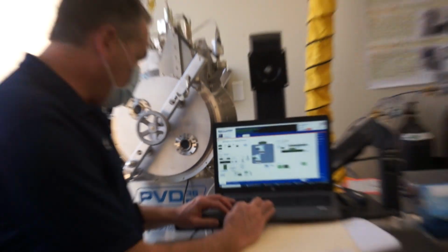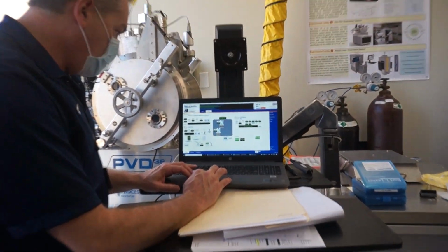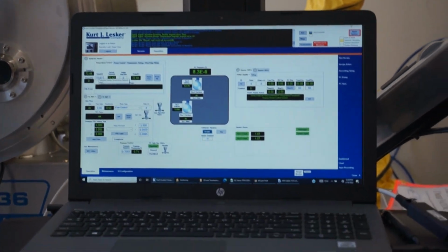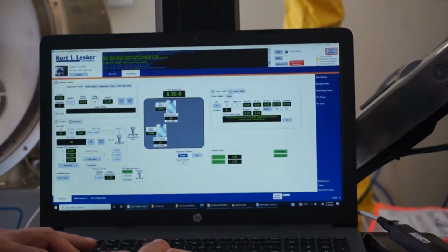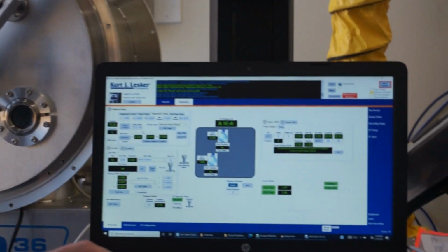I like to use temperature control. With temperature control, you actually put a ramp rate in and a desired temperature, and then it gets up there nice and easy. So you shouldn't have to play around with temperature tuning. These are all the PID loops we had set.